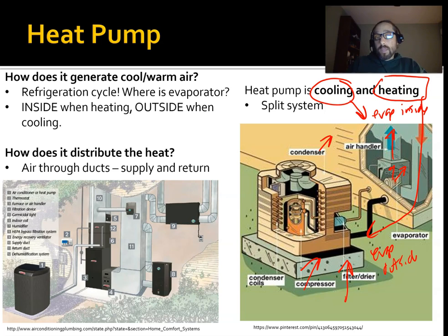Oh, and by the way, with the heat pump, because it's the refrigeration cycle, you're not converting electricity into heat. You're using electricity to drive the compressor. Remember, the compressor is what uses most of the energy, and that's what causes the latent heat transfer. The reason this is important is that if you put 1 kilowatt hour of electricity into a heat pump in heating mode, you're normally going to get more BTUs of heating than is in the electricity. That's because you're not converting electricity to heat; you're using the electricity to drive the refrigeration cycle.